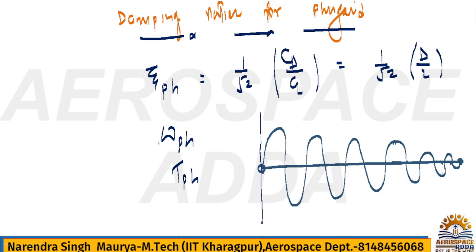To analyze that, we have the damping ratio, damping coefficient or damping factor. Simply, damping means reducing the amplitude. So related to amplitude reduction, we have the damping coefficient. Two types of damping coefficient we have: the natural damping coefficient, and the forced or critical damping coefficient. The ratio of the natural and critical damping coefficients will give the damping ratio. So that is the vibration part, and that's the reason I am not going into it. But you need to remember this damping ratio, because it is required.